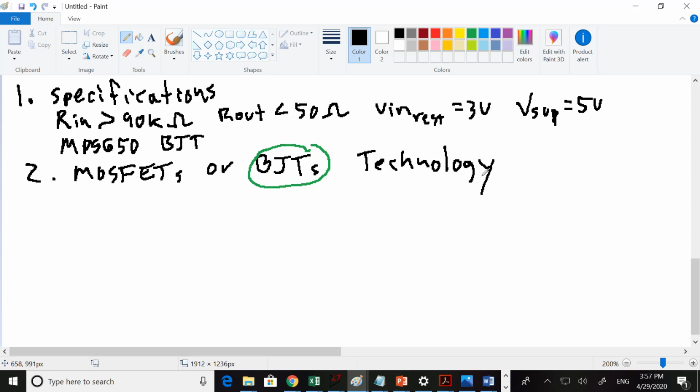So as you know, if you use a different transistor, you use a different model file. And the model file describes how your transistor behaves when you simulate. So the technology is actually the values in the model file. Maybe a higher early voltage or a smaller beta, something like that. The technology actually takes all of that into account. But generally in this class, I'll give you the models and just one of the decisions you may have to make is MOSFETs or BJT.